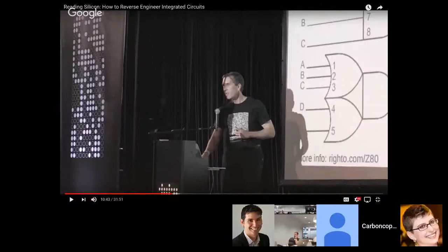In the next clip, Ken shows us how he was able to use the key steps of labeling and application of abstract models to read the program bits in the ROM, and how by reverse engineering the instruction set he was able to build a simulator for the chip on which to run the program.